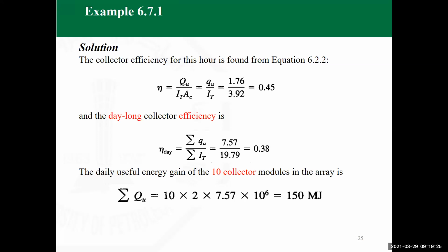And then the hot water is going to pass in tubes, and the tubes are going to go through different locations, bringing hot water to every room, either in the hotel or in the hospital. The 3-star hotels, for example, or below, are basically using electric heaters that are put separately for every room. Above the bathroom there is a false ceiling, and above the false ceiling they put a 1.2 kilowatt electric heater, like the one that we may have at home.